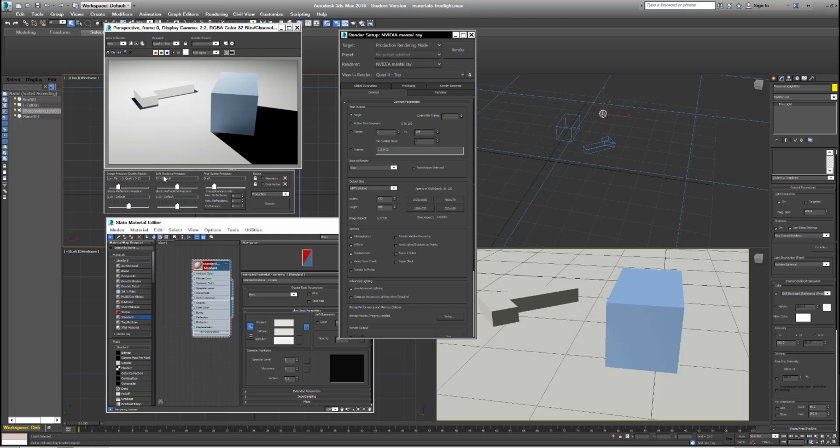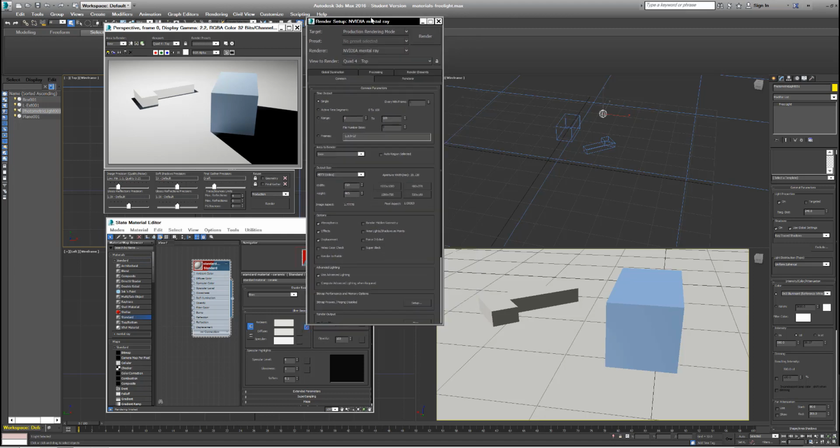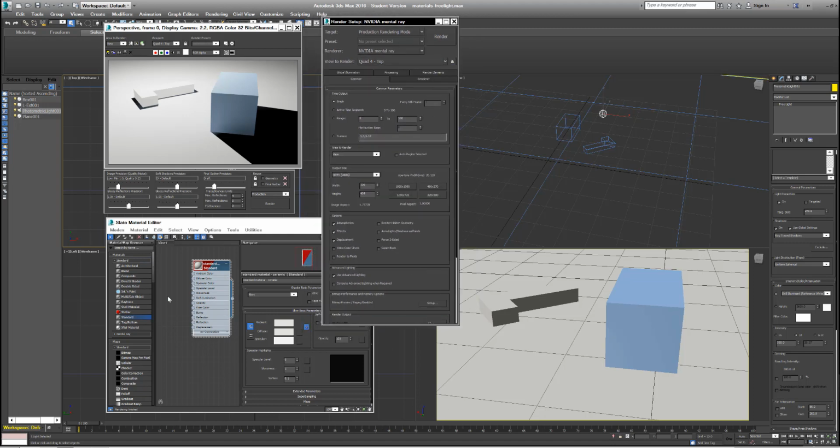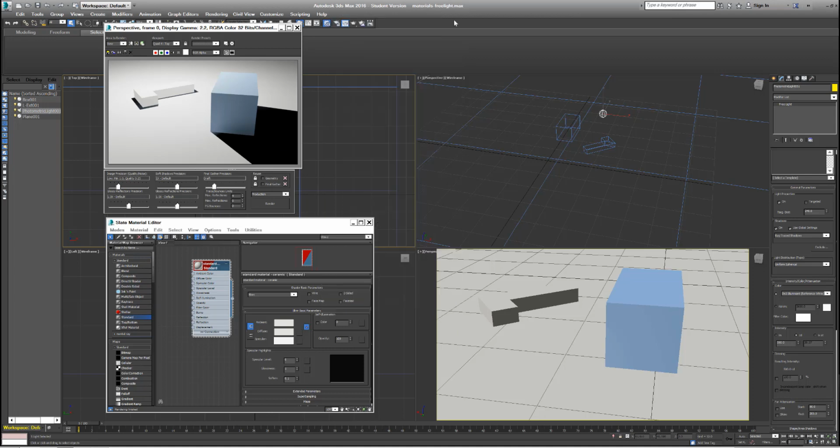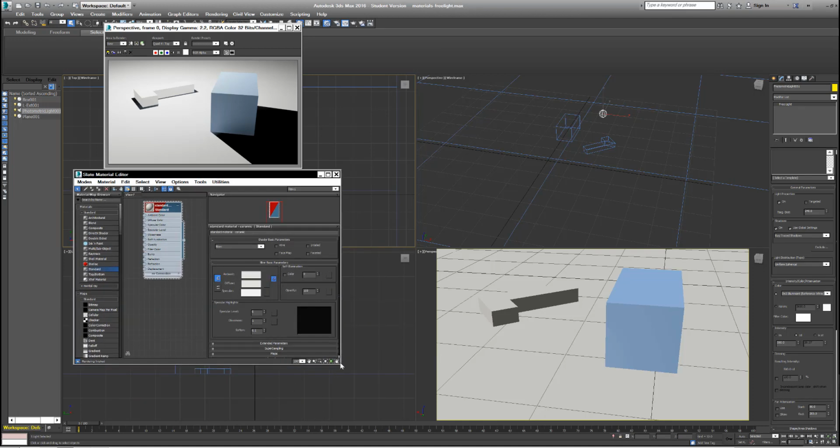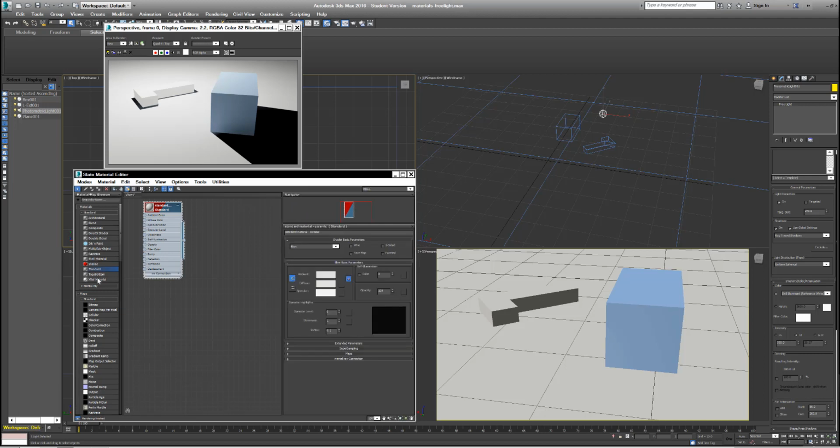It's very similar to if you've ever worked in Adobe InDesign or Adobe Illustrator and you don't have a certain typeface or font. It shows up as a default serif or sans serif. That is a similar thing. You need to use the renderer that's compatible with your material and the materials that are compatible with your renderer. So just make sure those two are one-to-one, make sure they're the same. Okay? So I'm just going to be working with standard materials today in my example because I believe you also have standard materials with the Arnold renderer.